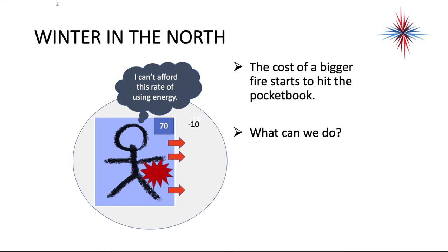Same with the cooling. Just because we're talking heating on this slide doesn't mean air conditioning is different. So along comes an installer doing the best job they can possibly do. They take a look at the size of the building. They say, well, wait a sec. This furnace is way oversized for this size of the building. And they put in a furnace based on the square footage of the building because everything's more efficient now. So we put in a lower BTU output furnace or a lower BTU output air conditioner, and all of a sudden, it doesn't do its job.